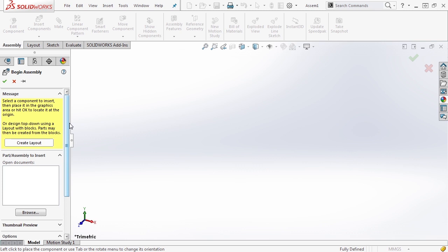And it gives us a few advantages. Assemblies can be lightweight, which means you don't have to fully load components. If you have very complicated parts, with lots of surfaces or thousands of features, you don't want to reload that every time you make a change, or you move or connect things, or just check the motion on them. Well, in an assembly, you can load it as a lightweight component, or you can go into a large assembly mode where you're really just loading a graphical preview of it, a very simplified outside shell. It still looks identical, but you don't have to load all the features and all that information. It's just simply redirecting to what that thing looks like.